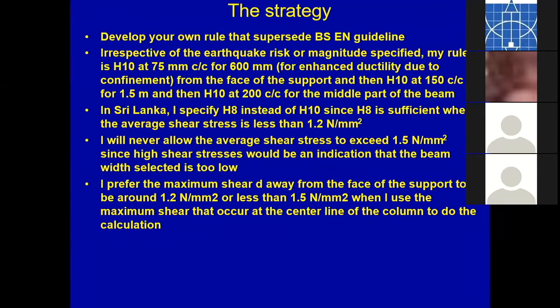So if the beam forms a plastic hinge, there will be plenty of steel reinforcement in the form of shear links to distribute the cracks. Also, when stressed, there will be sufficient confinement to the concrete so that the concrete will not crush. So there are so many benefits you can gain by going for earthquake based designs.